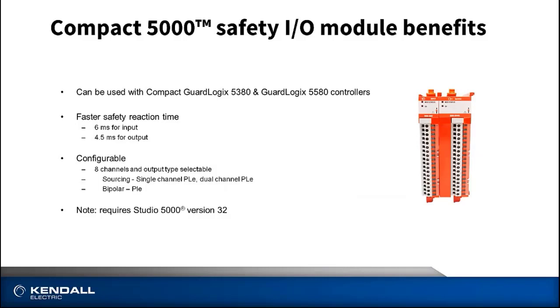A couple of the features that set this new I/O structure apart is a faster safety reaction time. For those of you that may have already used and deployed the POINT Guard I/O modules, you might recall that the safety reaction time on the POINT Guard input is rated at 16 milliseconds, and I believe the POINT Guard output safety module is rated at 6 milliseconds. So here we have an improvement in the safety reaction time.